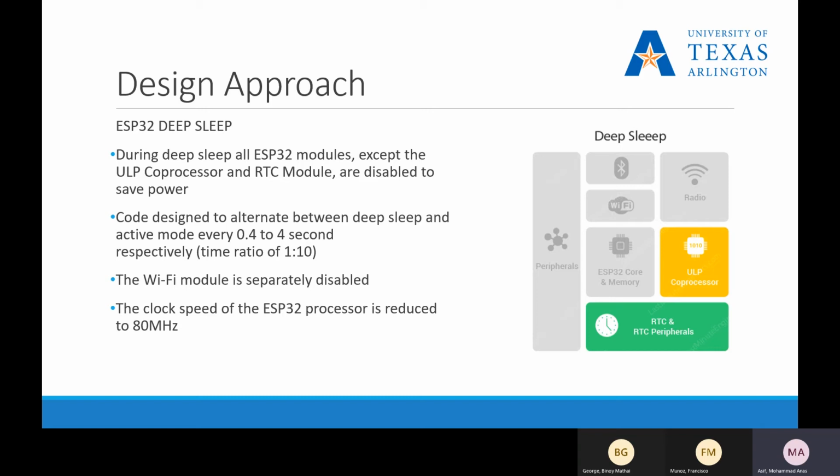In this mode, power is shut off to the entire chip except the RTC module, so any data that is not in the RTC recovery memory is lost, and the chip will thus restart with a reset. This means program execution starts from the beginning once again. So unlike other sleep modes, the system cannot go into deep sleep mode automatically. So special functions can be used to immediately enter deep sleep mode, as long as the wake-up sources are configured, which we did using code.